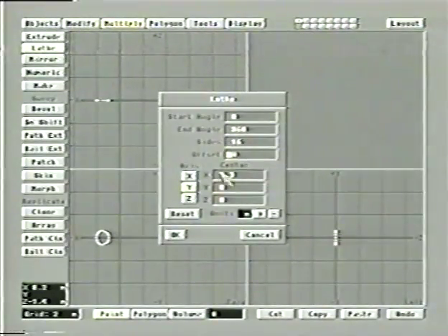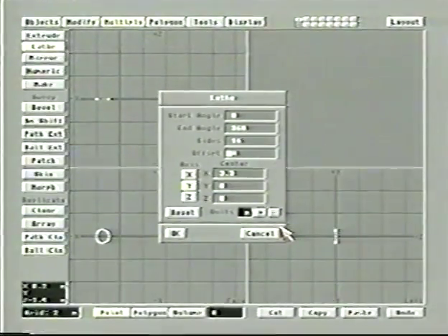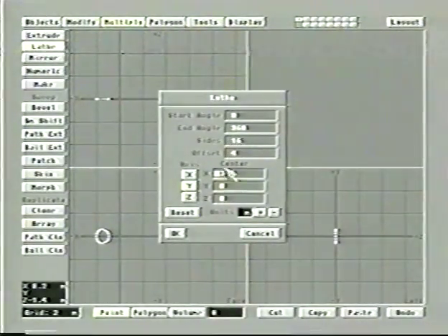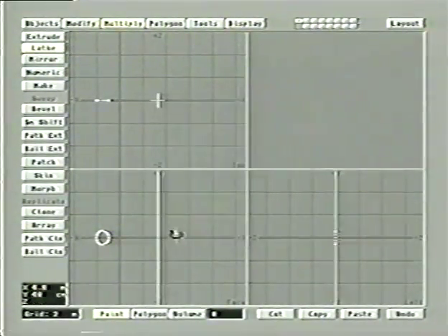One common shape it's useful for is one you'll see on the computer, a chord, for instance, where you've got a curly chord here. This is the kind of object that really throws people when they try to think about how to model it. Watch how easy this is. Here's the idea. We'll set our offset to, let's say, 2 meters. Actually, let me set it a little bit more. I can see my grid is 2 meters here. Let me set it to 4 meters. 360 degrees, 16 sides. I'll just leave everything right there.